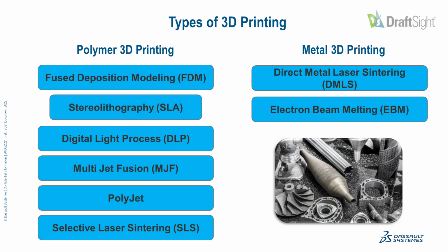The next type of printer is similar in technique to SLA. Being a resin 3D printing process, this is digital light processing, or DLP. This is where a light source cures an entire part layer at once by projecting an image of the layer cross-section onto the build plate. This in turn allows DLP printers to be faster than SLA printers.